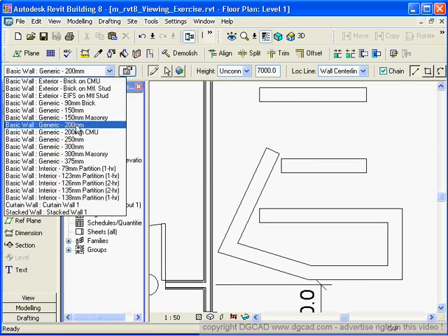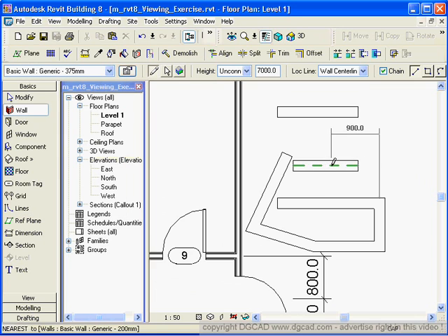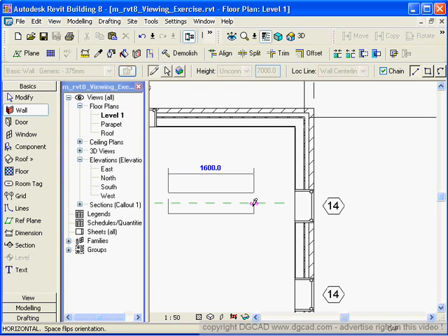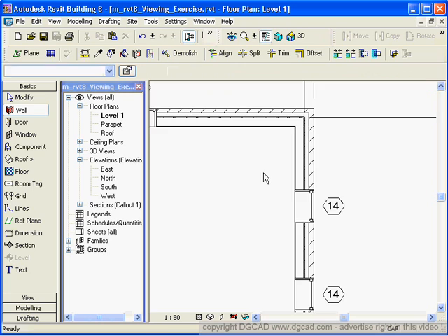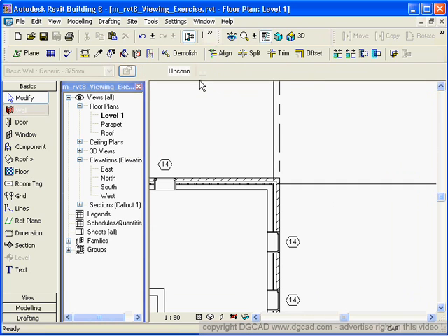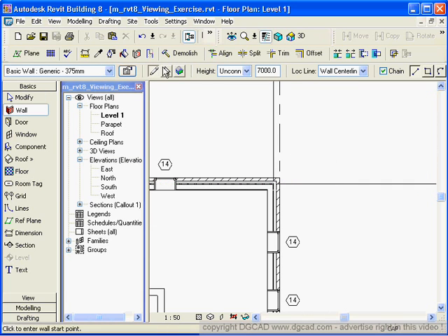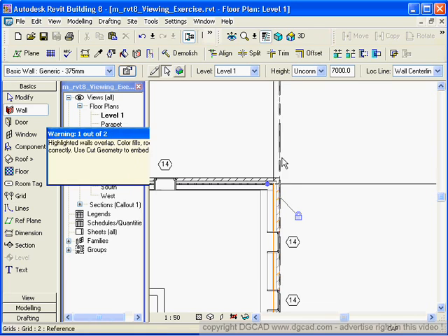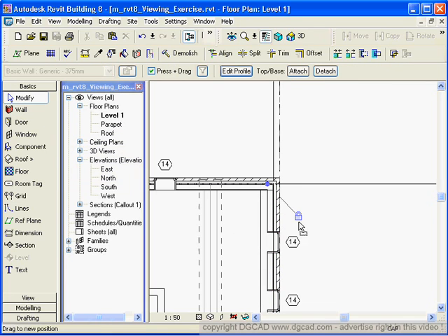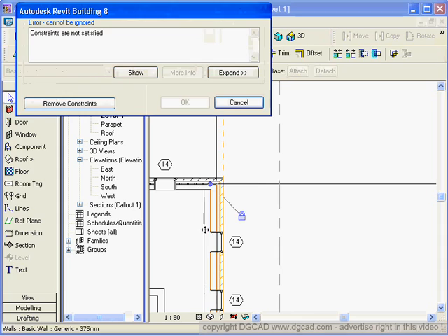So as you're placing a wall, you can pick your wall style off of here, whatever wall style you want. And then as you're placing it and clicking, you can type in a number anytime you want. You can also make a wall by surfaces, we'll see with solids, and we can also go by picking on line work. So if we draw a wall, we can pick on here, and then pick on that point, and it's actually going to put a wall right within the wall, but that's okay. And now I'm going to take this and maybe move that over there, something like that.